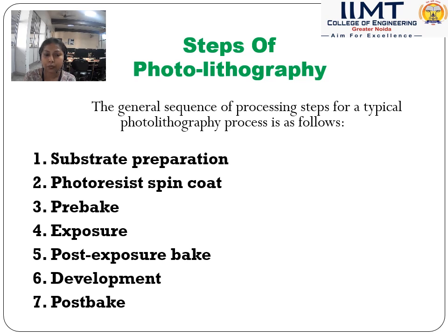After that, the photoresist spin coat technique. The third one is pre-bake, the fourth one is exposure, then post-exposure bake, the sixth one is development, and then post-bake.